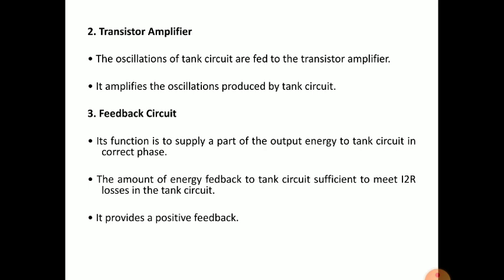resistive components. The resistive effect of the capacitor and the resistive effect of the inductor in the tank circuit will also come into effect, and because of resistance the current I into R voltage is produced and the power loss P is equal to I square R losses will also be there. So after a certain time the voltage whatever we apply to this tank circuit will keep on discharging, decreasing, and become zero, but it should not happen in an oscillator circuit. That's why we provide a feedback circuit.